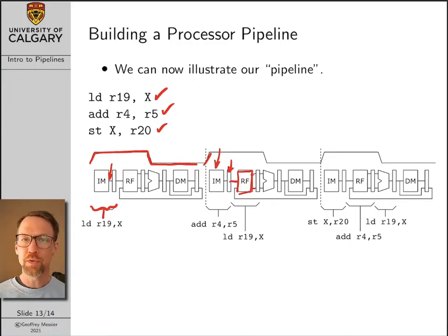Like in our old single cycle design, the whole purpose of the instruction memory, once the instruction was fetched, was to just hold everything stable so that the stages that followed in the microarchitecture could do their work. However, the pipeline register is keeping things stable, so we can set the instruction memory stage to work on the very next command.